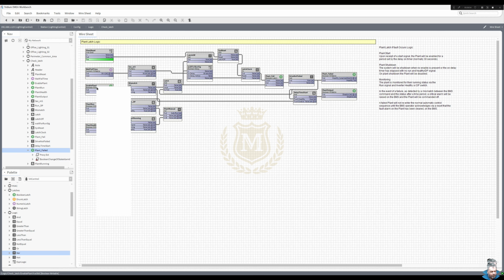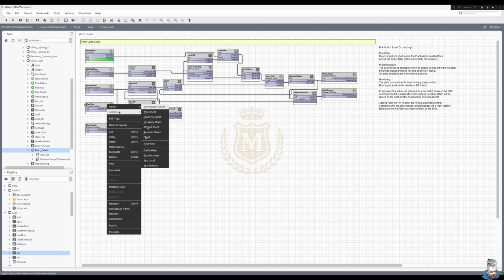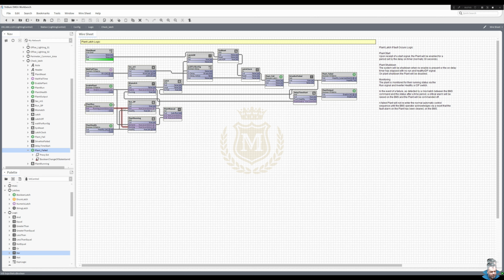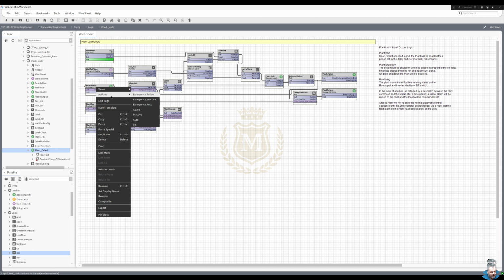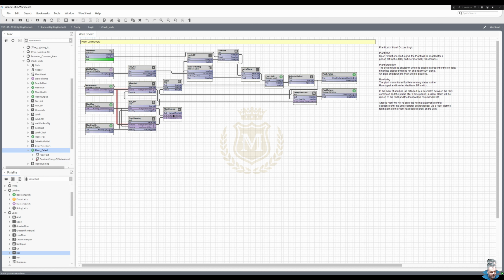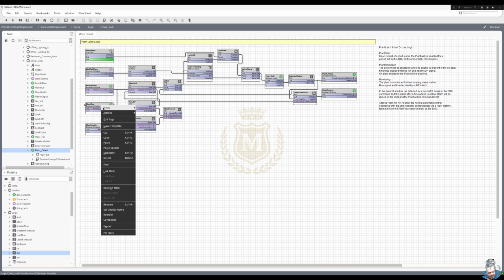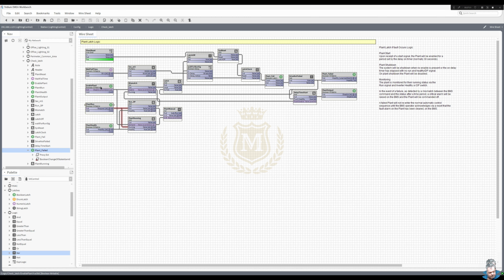So if we have put the enable on and we don't have the plant run, we're in manual. If we have the plant run, we're auto run. If we have the enable off, but we're getting a running, we've got a manual run. So it's just a mismatch between them two, i.e. someone could use the switch, turn off the controls, put it to manual run, we get the running signal, so we know the system's in manual run. Well, that's the idea behind it.